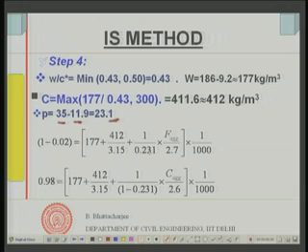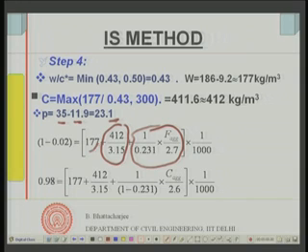That means the volume fraction of fines in the total aggregate. So, volume of fines is the mass of the fine aggregate divided by the specific gravity of the fine aggregate. That is the volume of fine aggregate. If I divide this by 0.231, I get the total aggregate volume. So, this is the total aggregate volume, this is the volume of the cement and this is the volume of the water.